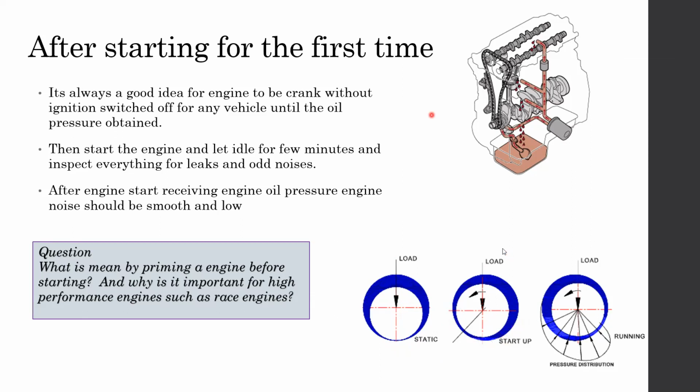But the problem here is the force acting. If we rotate, the crankshaft is rotating freely while moving the piston, right? But if you start the engine at once without any priming, the force from the combustion is acting on this crankshaft without any fluid to lubricate it, without the oil pressure. So it's not advisable. It's always better to prime the engine.